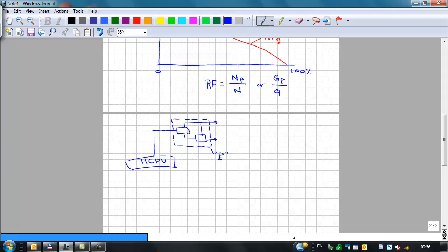That's the way I draw it: P, capital P with 2 lines under it. It's any process you like. We're going to use a 2-stage, or maybe a more complicated one, and we end up with, if we take all of the contents of this hydrocarbon pore volume to the surface at once, that's what the reservoir simulator will do, to tell you how much sales gas is there. This is our sales gas. Okay, and we play God. We just take everything from the reservoir through this process to the surface.